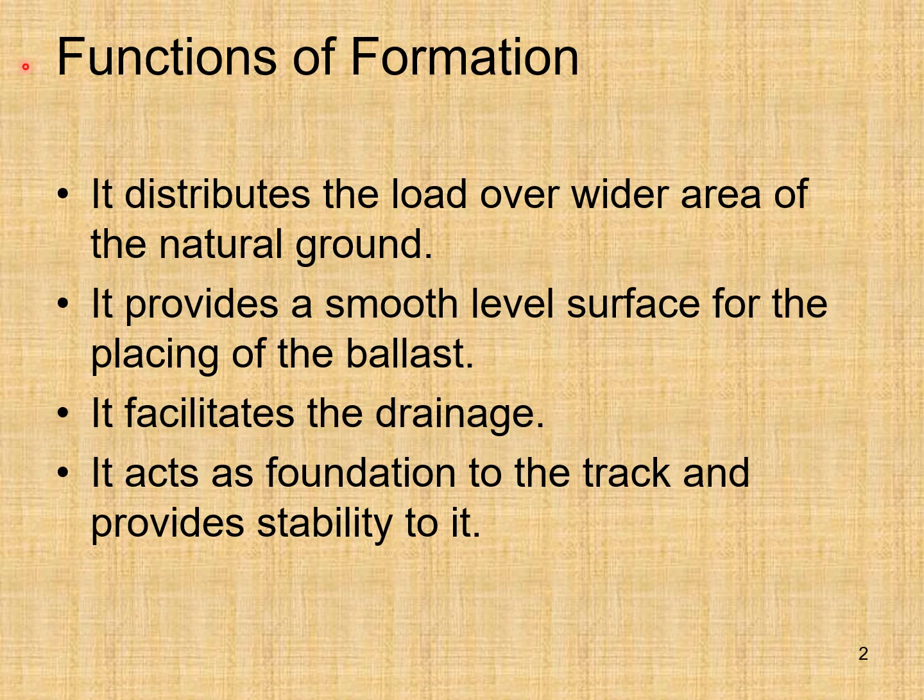Functions of formation. It distributes the load over a wider area of the natural ground. It provides a smooth level surface for the placing of the ballast. It facilitates the drainage. It acts as foundation to the track and provides stability to it. So this function is very important.